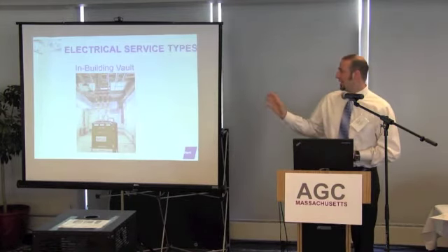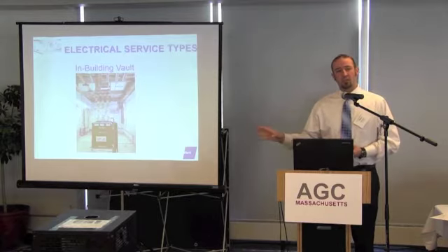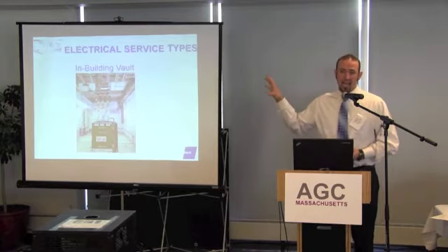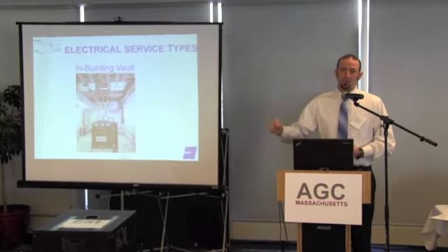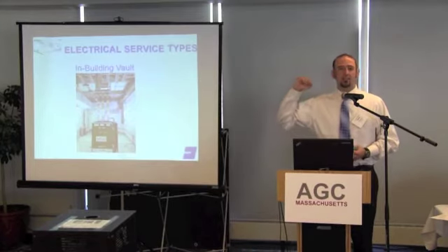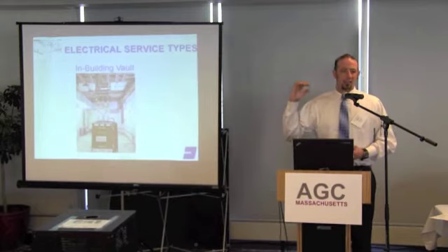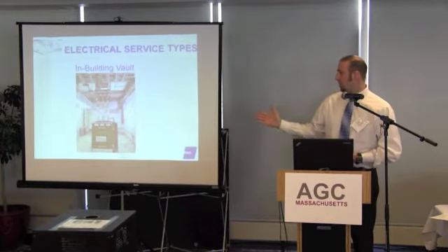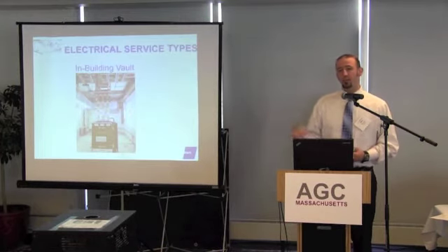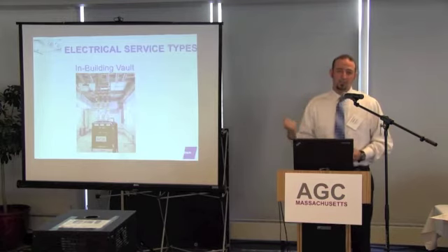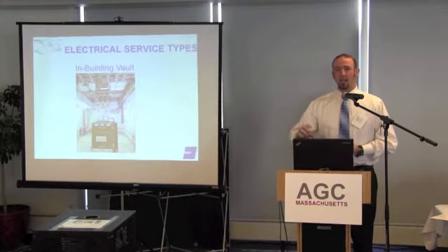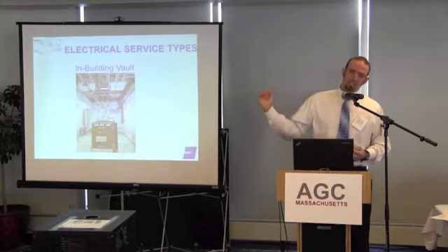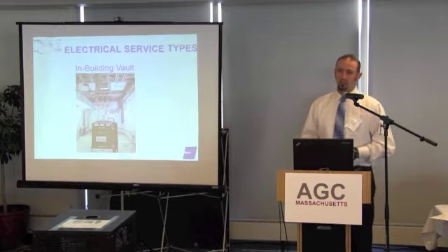Usually NSTAR will take about 6 weeks to re-engineer anything that's going into the sidewalks, because those sidewalks are full of water lines, steam lines, 13.8 lines. I'm actually working on a job right now on New York Street where we're submerging one of these things, and it is a hassle to coordinate with the building, and then you have to coordinate the inverts into the building.